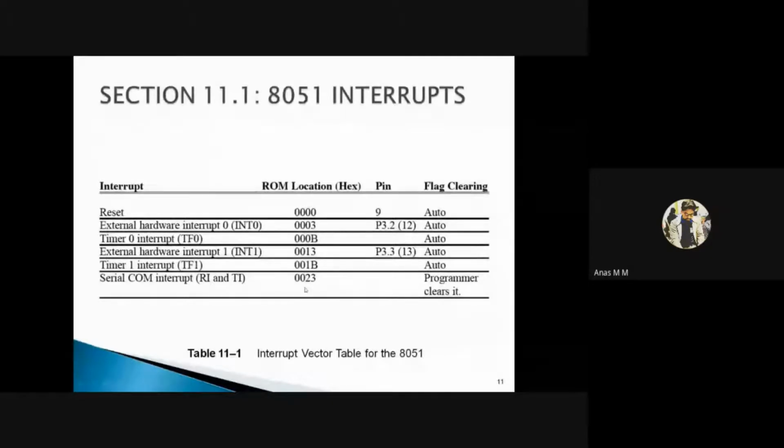So what do we understand from this? From now on, when we program, we need to take into consideration that we have interrupt hardware in 8051. Whenever there is an interrupt request through that hardware to the CPU, it will jump to these locations. So what can't we do when we program now? We should not use locations 0002 to 0023, because these locations are used for interrupts. Understood?